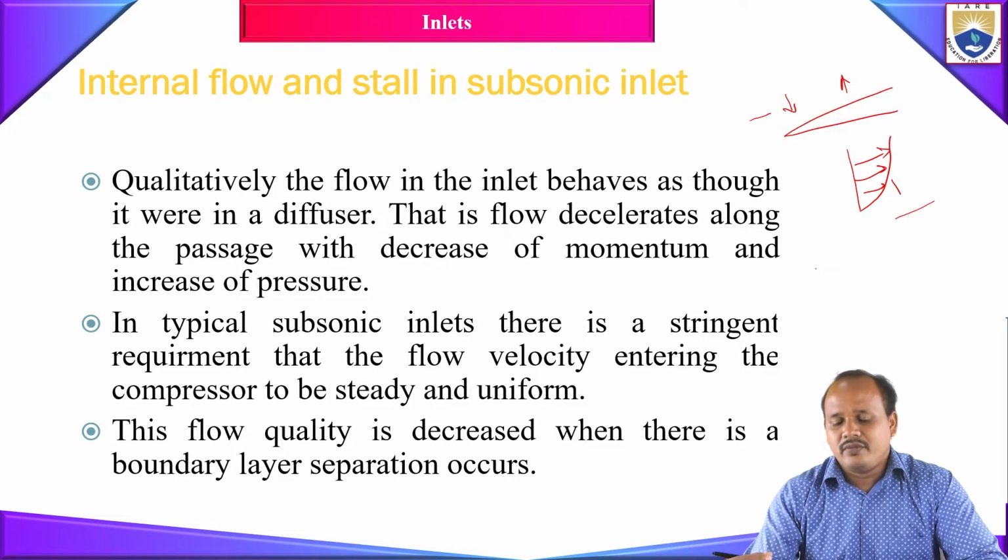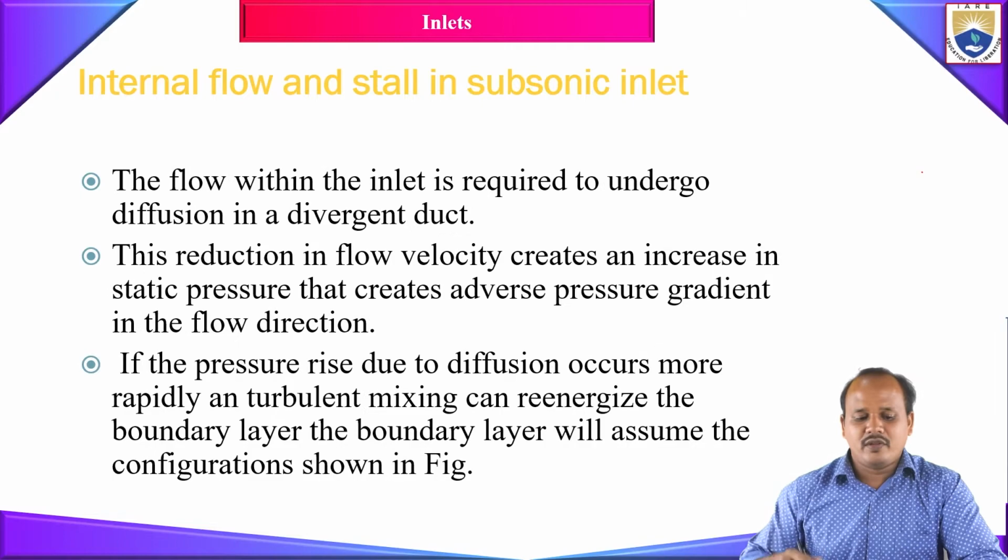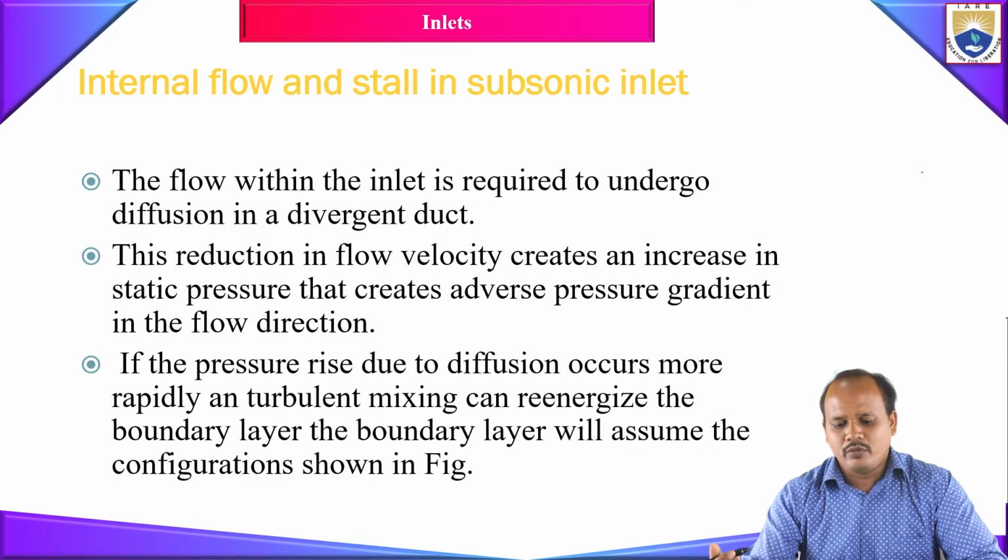Okay, so once your flow starts moving in the reverse direction, that's when your flow is going to separate, or your boundary layer is going to separate. You can ask, what happens if the boundary layer separates, or why do we bother about boundary layer separation? Whenever the boundary layer separation is happening, you will have the formation of wakes and vortices. And one more thing is that when the boundary layer separation occurs, there is going to be a loss in the total pressure. Total pressure loss will happen.